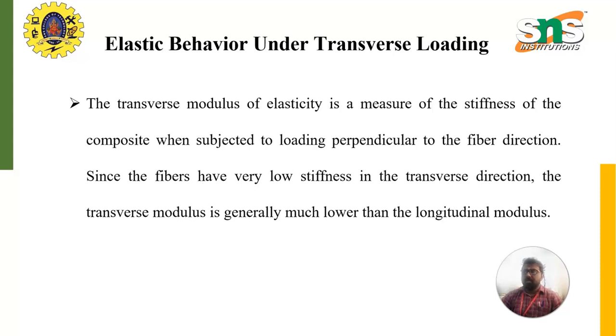Here, the elastic behavior under transverse loading: the stress-strain relationship is more linear for lower loads, but the composite is much less stiff than in the longitudinal direction. Due to the low stiffness of the matrix and the limited load carrying capacity of the fibers in this direction, the composite can undergo significant deformation under transverse loading.